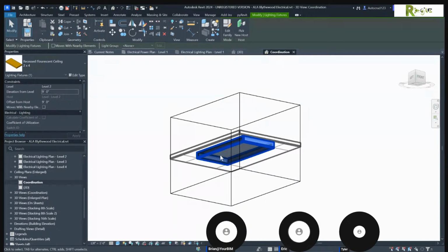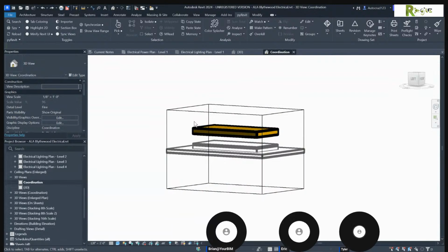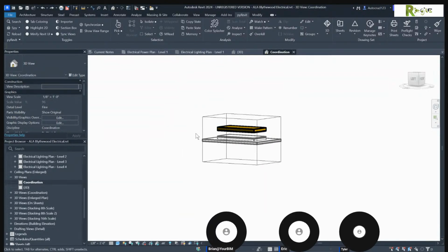Theirs is wrong. Gotcha. But when you go back to the floor plan to select all of them, you're going to have one that you have at 9 feet and the rest are at 10. How are you going to get them all down to 9? I was just making sure that was the right number before I went crazy. Go put them at 9 and then go look at your power plan sheet and you'll see it should have covered those black spots up.